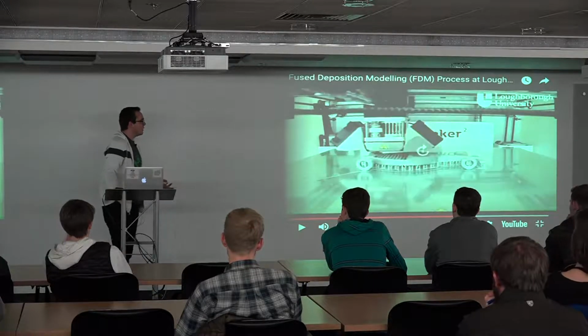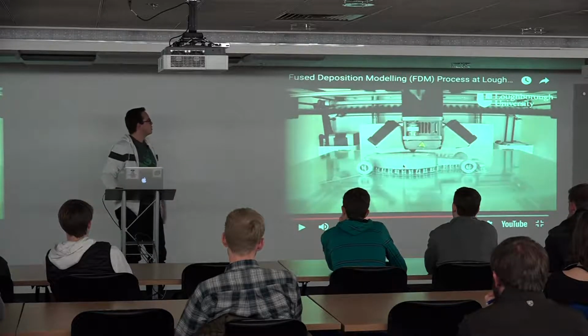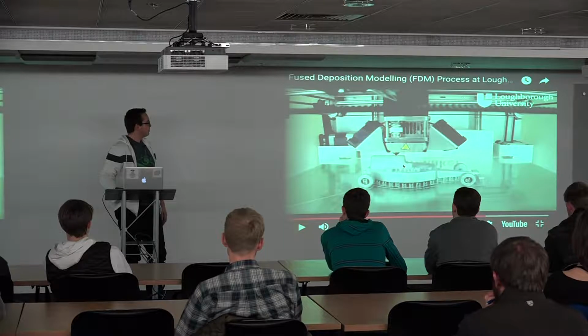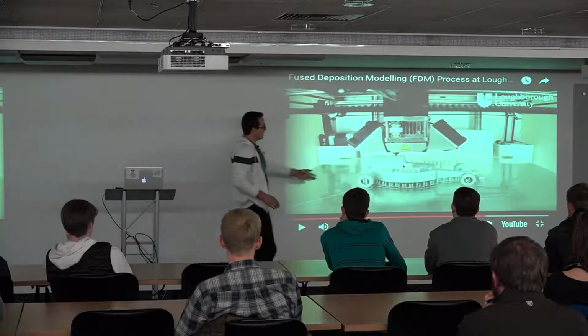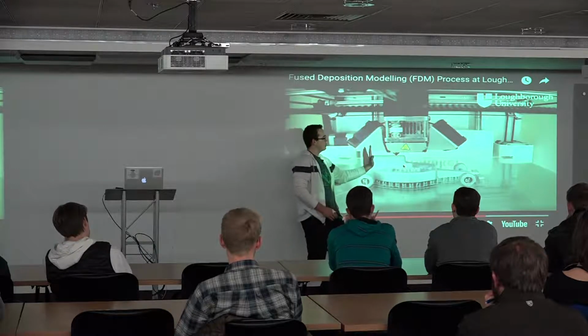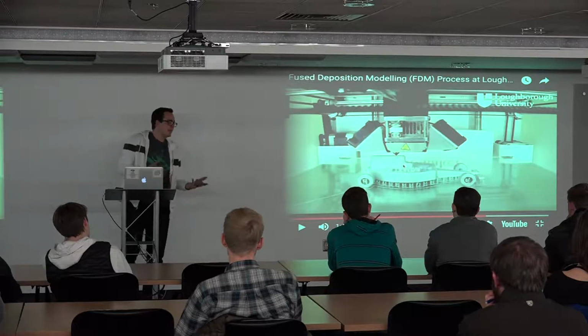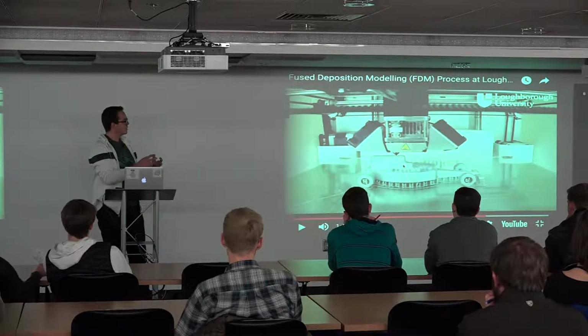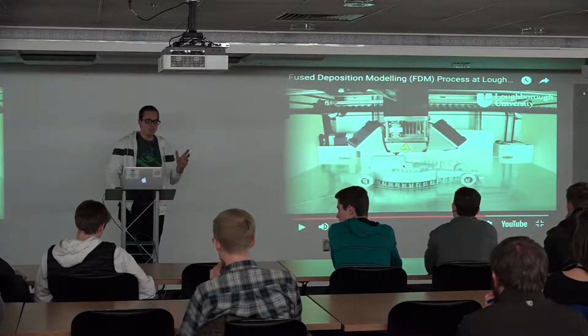If your part isn't designed for 3D printing, like Formula One race cars, then you just kind of do the best you can. Although you can sometimes find better orientations for printing things. Like for example, they could have flipped this car up and printed it more vertically and needed a little less support, but then again, it might not have had the right detail exactly the way they wanted it, so it just depends.